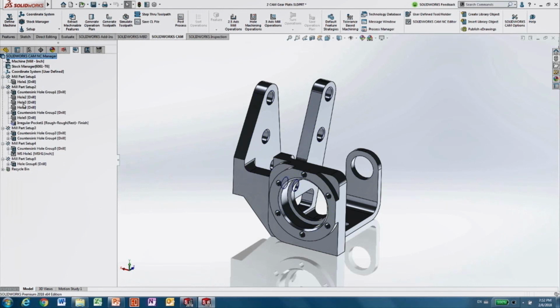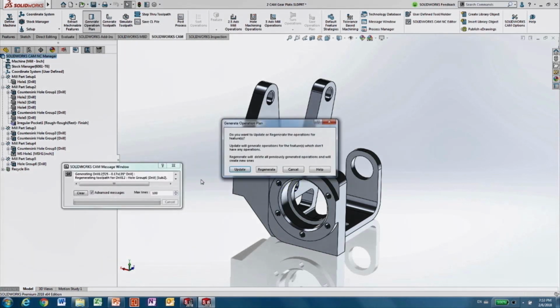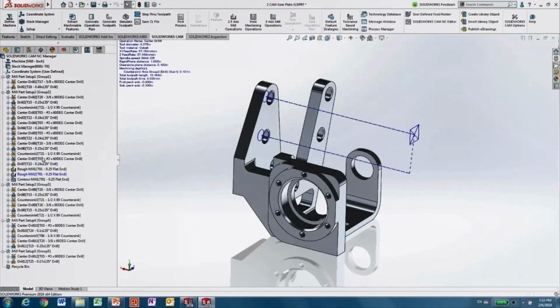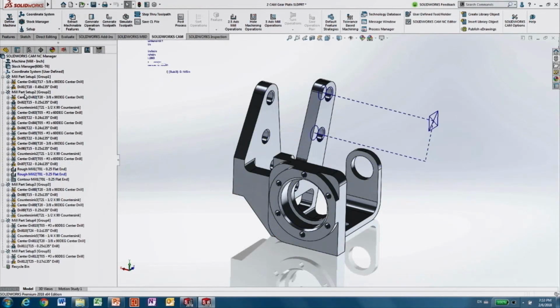And then when you generate the toolpaths, based on the template that you created for your company, you're automatically going to simulate the whole machining, the G-code and all that. And it will point out if there's any issue. It will point out if you need some tools that are not in your tool sets, and things like that. And again, entirely integrated, you can see it's pretty quick.